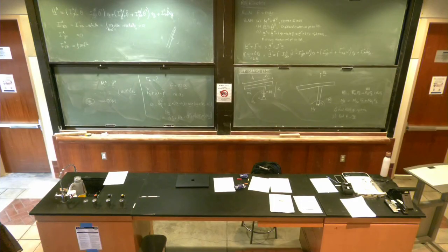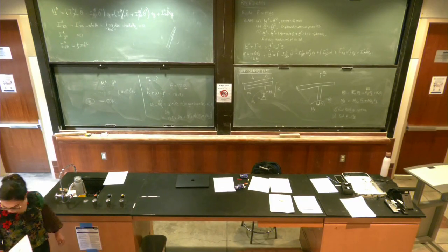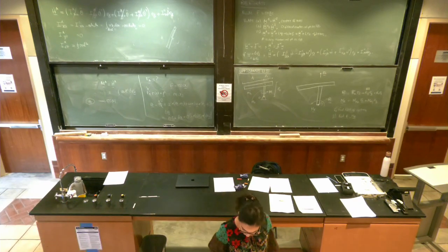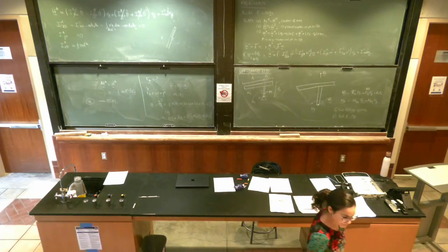Why is the weight force at the end of the bar? Why is the weight force at the extremity? I'm just marking it out. But yeah, be careful. The weight force will be at the center. Oh, okay, I see. The bar is off center. Perfect. Then the reaction force, reaction moment, and that's it.